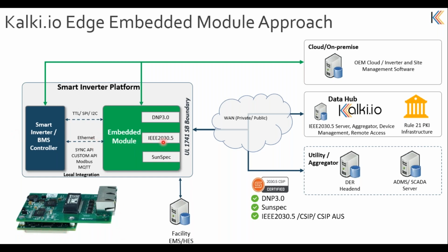And the software integration and the data exchange integration can be through any of the protocols, like an API-based approach, standard REST APIs or WebSocket APIs or MQTT, Modbus, or any custom APIs can be used for exchanging data from the inverter platform with the OEM module or this particular board which you can see here.